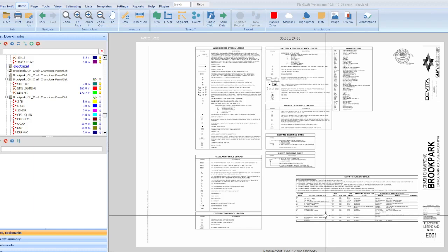And in the neatest way you can, because if you're an electrician, you're not just going to throw the wire all over the ceiling. Everything that's going to one panel, you'll probably be running together somehow, gathering it all on one side of the building. And if another panel is in the middle of the building, then you're going to route everything towards that way. So that helps too.